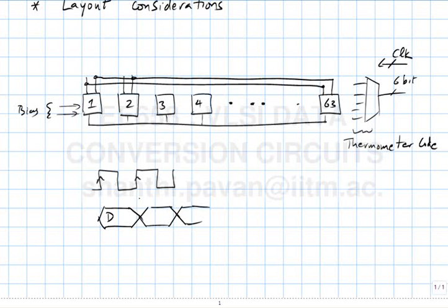One could argue that I could take the 6-bit word, and propagate it along the entire array and locally generate the logic which goes and enables the DAC. An argument against that is that the digital logic that I need to use to generate this is likely to blow up the area of the cell, which means that matching will now be compromised. So a reasonable thing to do is to generate the 63 lines somewhere and propagate the 63 lines. Of course, now you are stuck with the problem of propagating these 63 lines. Okay, that's one of your problems.